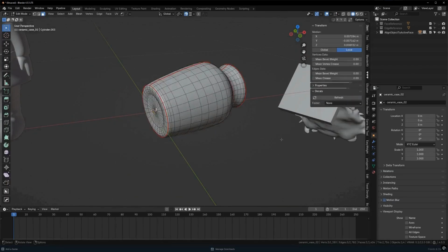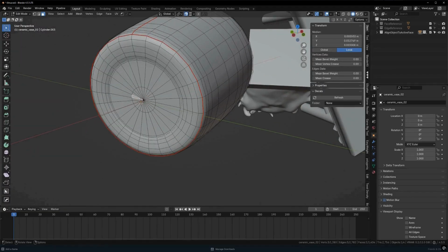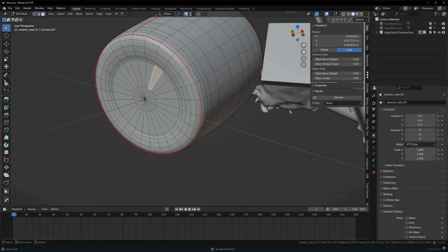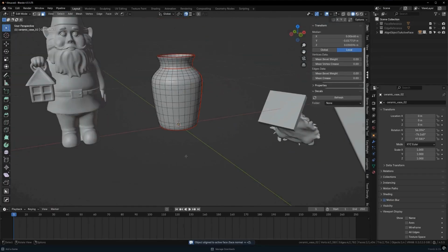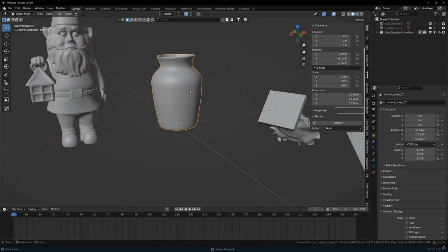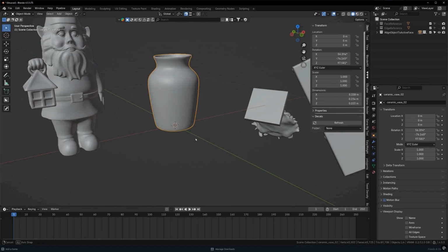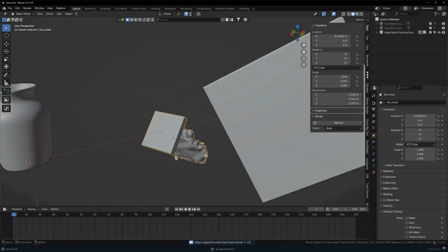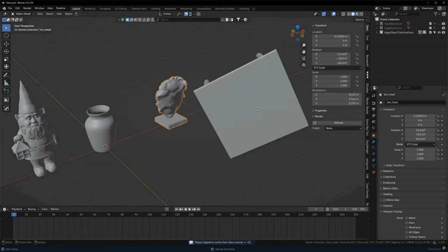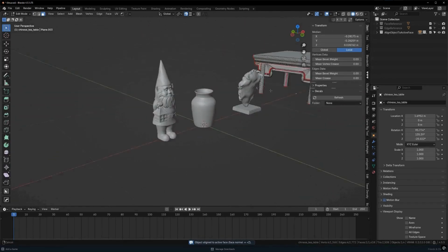With ReFace, you simply go to edit mode. So you select any flat face and then you right click and then you select align object to the active face. As you can see, it aligns it with the z-axis of the world coordinate system. And then if we go out, the rotation is not applied, so you can still Control Z and go back to your original rotation. And then if I go to each of those objects, as you can see, it's very easy to fix that rotation.